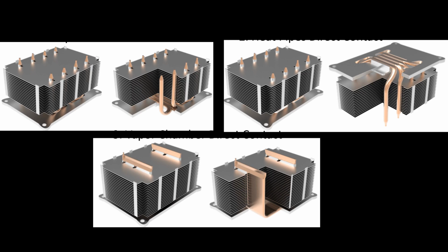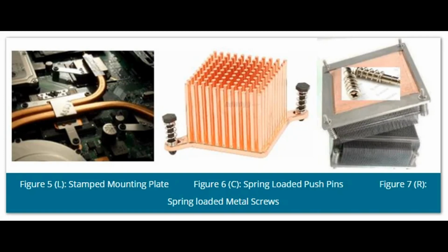While thermoelectric heat sinks offer precise temperature control and versatility, they are less efficient than traditional cooling methods in terms of energy consumption and heat transfer efficiency. Additionally, they may require additional power and generate waste heat, which must be managed effectively to prevent overheating. Despite these limitations, thermoelectric heat sinks remain a valuable cooling solution in applications where precise temperature control and compact design are paramount. Each type of heat sink has its advantages and is chosen based on factors such as the heat dissipation requirements, space limitations, and cost considerations of the specific application.